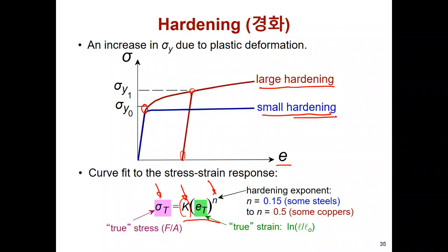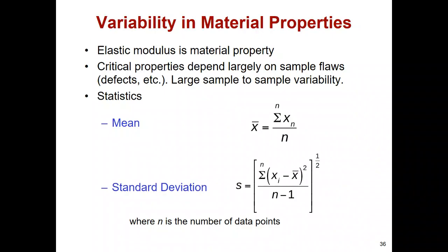However, in this other region the value is slightly changed to K and looks like this. To fit that slope, we apply a power hardening value. If we have a small value, we can express a small hardening. But if we use a very large value, the strain effect is dramatically decreased. Anyway, to fit that value, we just use the empirical value.